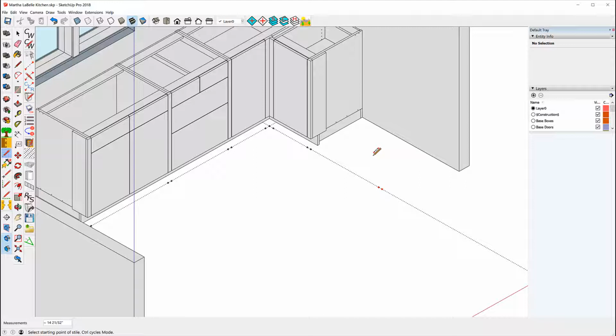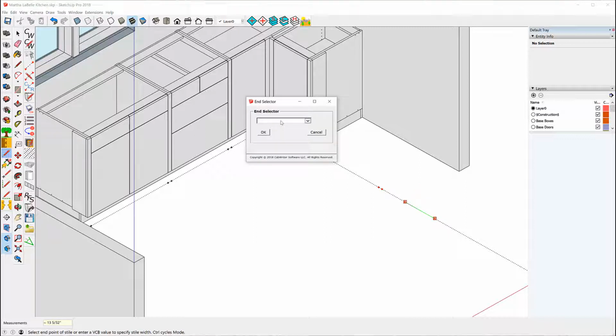And if I remember correctly, it was 24 3/4 of an inch to the pivot point on the Peninsula. So I'll start here, go 24 3/4 while I'm on the line. And I'll come back, click anywhere on the line. And this one wants to be a right pivot sheet.